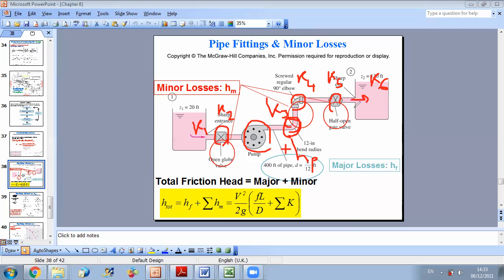And again, here, please pay attention for something also. In general, when you have, for example, an inlet, the K coefficient is related to the velocity after the reduction. While for the exit, the velocity V you multiply by is the velocity before the expansion. So always in the table or in the graph they give you, they will tell you K is multiplied by which velocity.